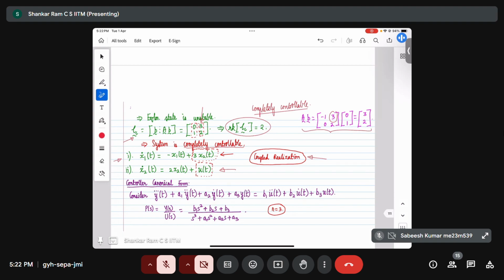But you and I may ask the question, in this equation for x1 dot, where is u? A natural question may come. Then why do you think the state x1 has suddenly become controllable while previously it was not? Because x2 is being controlled by u(t), and hence x1 will get controlled by x2 in that sense. So u(t) is controlling both x1 and x2, x1 indirectly.